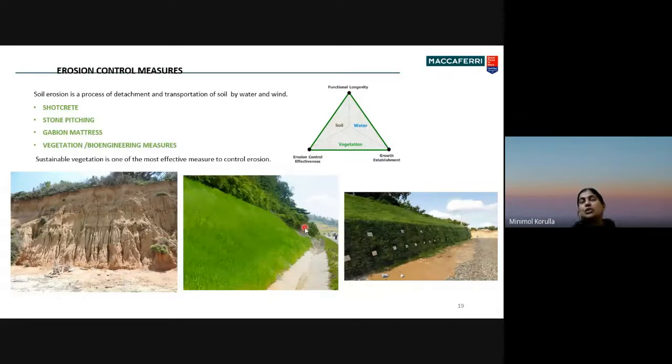What is being used is an erosion control mat, like a coir mat, with U pins for making it hug the earth, and then doing some seeding. If it is a difficult place, the steepness is quite high.